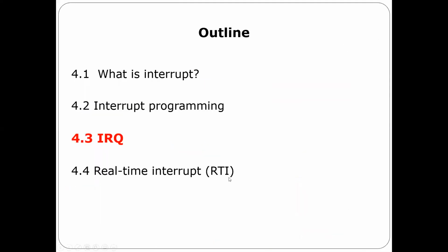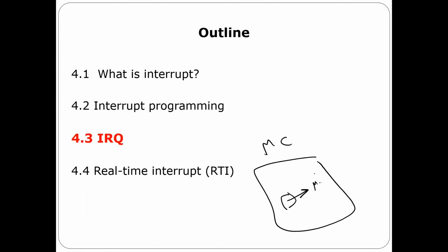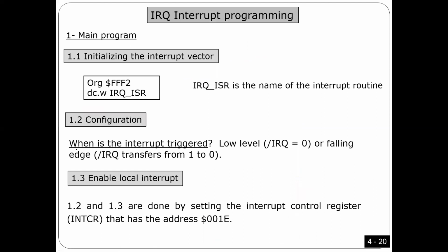Remember, RTI does not have an external pin. This is a timer, and this timer is inside the microcontroller. It is connected to the microprocessor to trigger interrupts. So there is no external pin here. This one, IRQ, has an external pin.